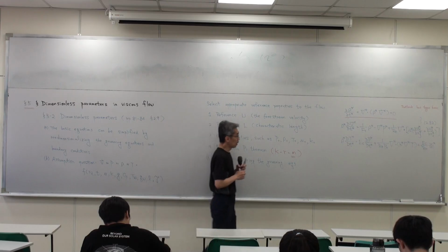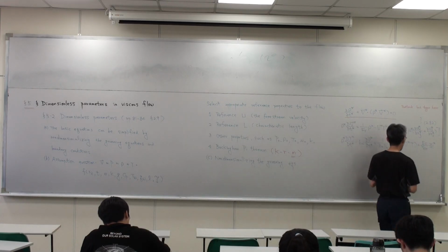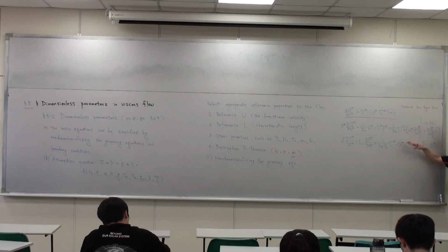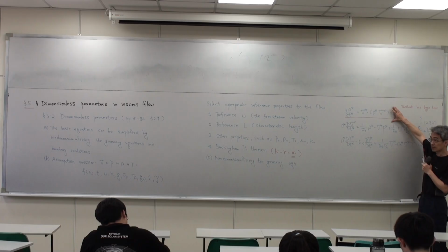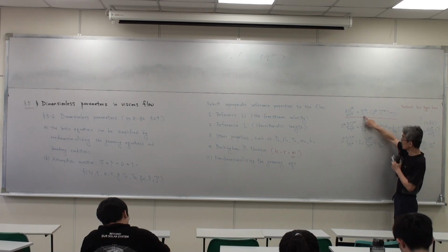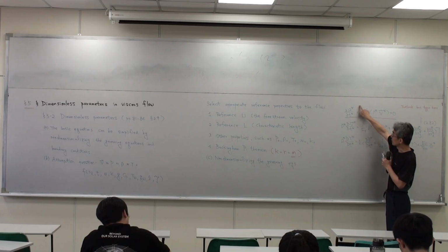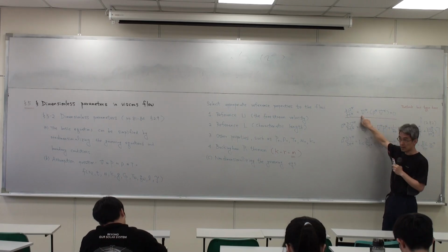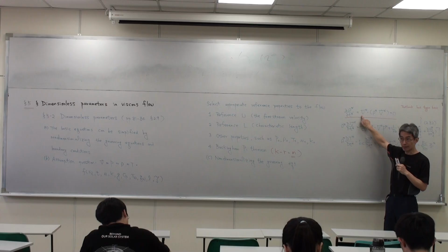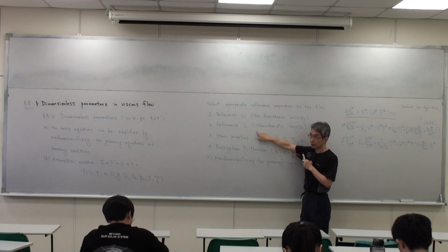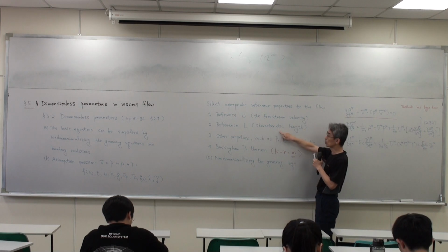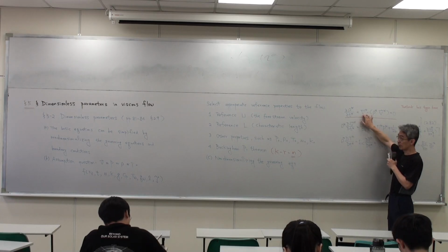So after we do the non-dimensionalization, I think you can practice by yourself, so I will not do that procedure. For the mass conservation equation, I think there is a typo here, because this is a space derivative. You must make your space derivative non-dimensional by the length. Choose the characteristic length to make this space derivative non-dimensional.